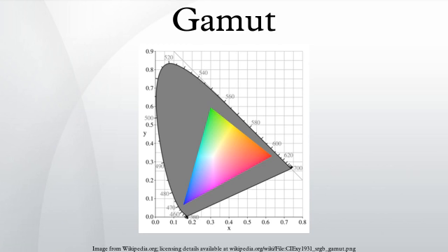The systems work either by scanning the entire picture a dot at a time and modulating the laser directly at high frequency, much like the electron beams in a CRT, or by optically spreading and then modulating the laser and scanning a line at a time, the line itself being modulated in much the same way as in a DLP projector. Lasers can also be used as a light source for a DLP projector. More than 3 lasers can be combined to increase the gamut range, a technique sometimes used in holography.